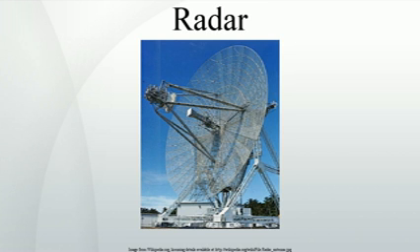Radar sensitivity and power of the return signal is computed in the radar equation. This includes factors such as environmental conditions and the size, or radar cross-section, of the target. Noise. Signal noise is an internal source of random variations in the signal, which is generated by all electronic components. Reflected signals decline rapidly as distance increases, so noise introduces a radar range limitation.